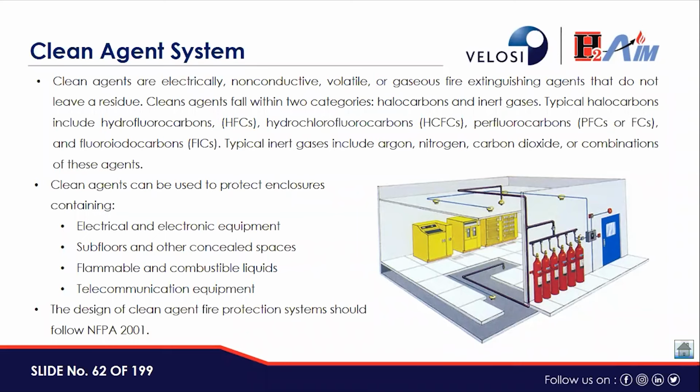These can be used in substations, which contain electrical and electronic equipment, subfloors and other concealed spaces, flammable and combustible liquids, and telecommunication equipment. So for the design of this clean agent system, we have to follow NFPA 2001.